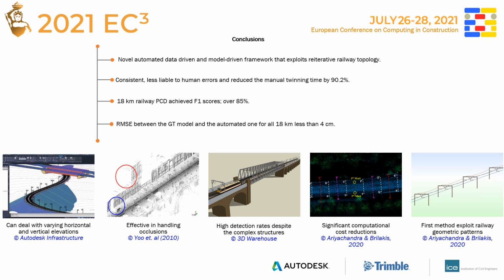This method offers significant computational cost reduction by automatically cropping a lengthy railway point cloud into relatively straight segments. This enables considerably improved large-scale object detection, generally required over kilometers, without forfeiting precision and manual cost. Therefore, we conclude that this is the first to automatically and robustly solve the generation of geometric digital twins of railway track structure and superstructure elements from railway point cloud data by exploiting repeating railway geometric patterns over kilometers of spans without needing any prior information about the input dataset.